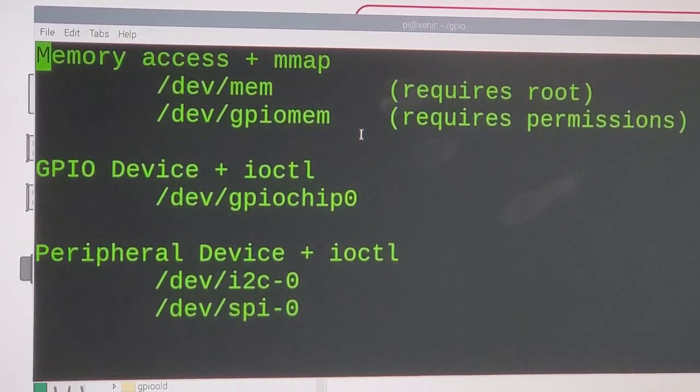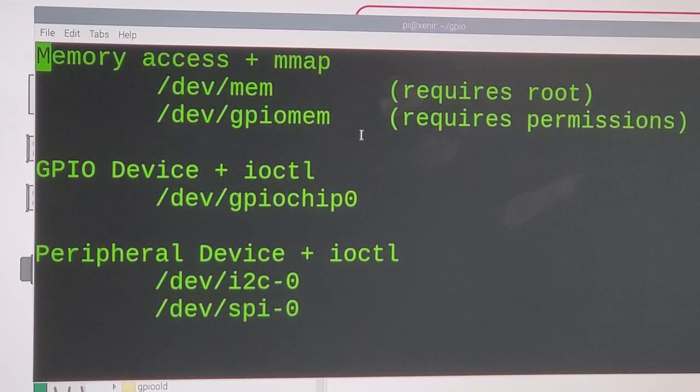But as I go through these examples, I'll start with just some bare bones access without using the libraries, just to show the flavor of how you actually access the devices, the sort of permissions you've got to have, how you access the different registers involved. And then for the follow-on SPI and I2C examples that I have later on, I'll be using the BCM2835 library.